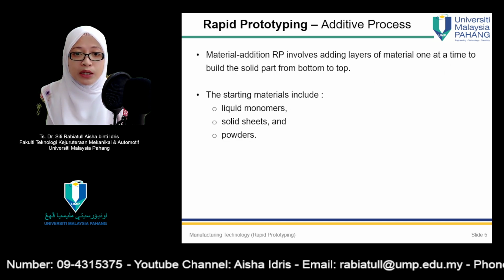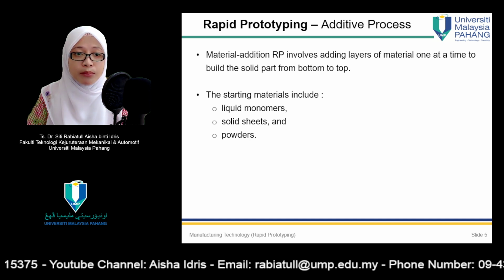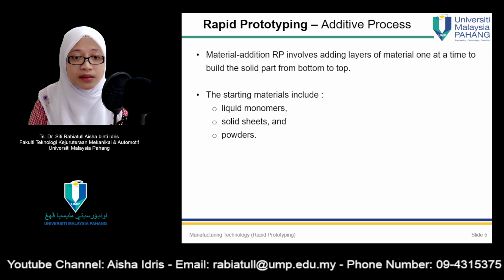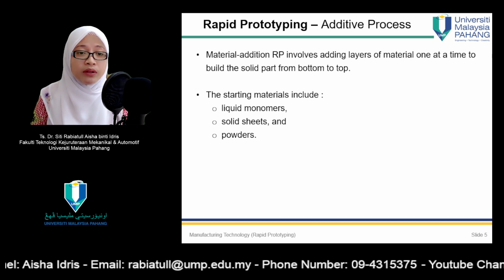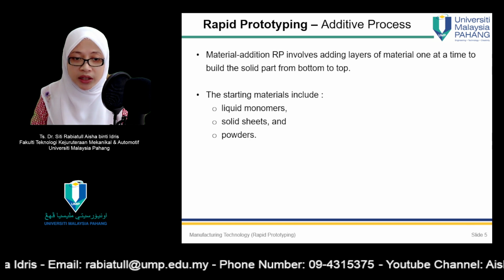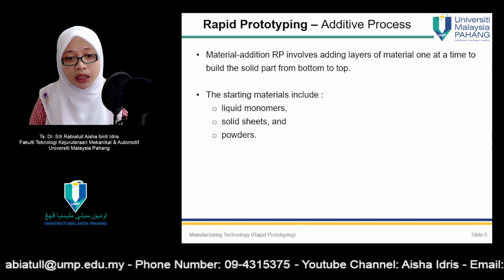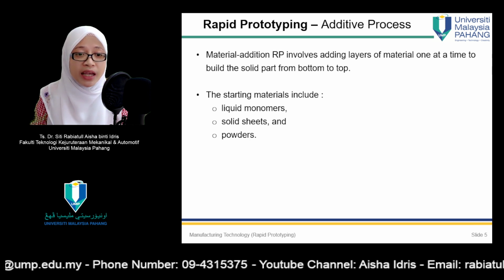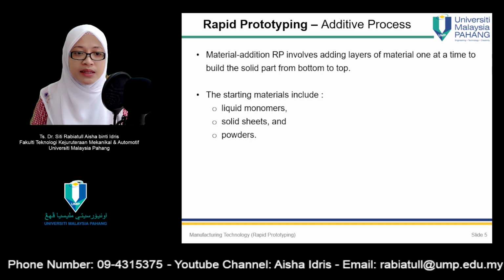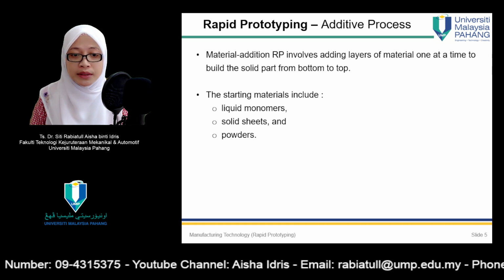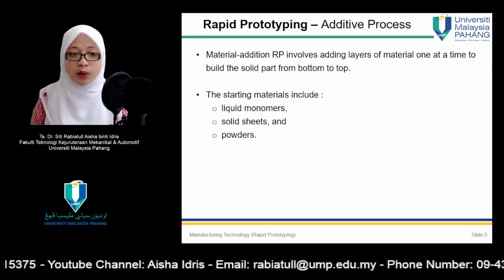Available RP technologies can be divided into two basic categories. Number one is the material removal process, and number two is the material addition process. The material removal RP alternative involves machining, primarily milling and drilling, using a dedicated computer numerical control (CNC) machine that is available to the design department on short notice. To use the CNC, a part program must be prepared from the CAD model.